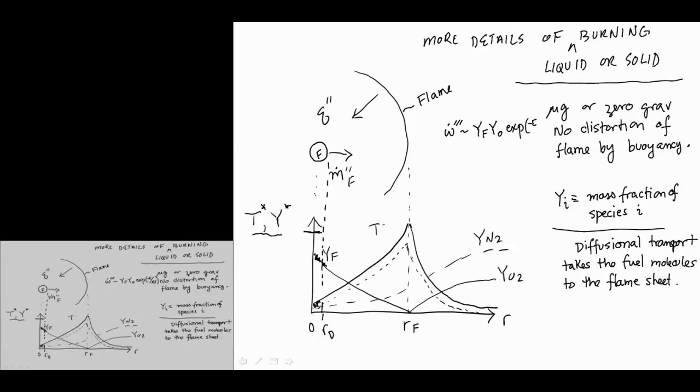Now, in a scenario in which reactions are much faster than the transport timescales, so when the reaction characteristic time is smaller than the transport time, the flame is infinitesimally thin, and YF and YO cannot exist together, and it's an idealization.